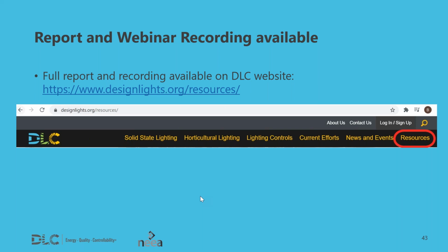Thank you. Yeah, I'm just going to add a little bit to that, in that one of the things that we see is that LEDs tend to be perceived as brighter, so when the new systems get put in, a lot of times they're lowering that trim down. It's not that it's a bad design, they put in the same lumens or whatever, but you do see that trim brought down because it feels too bright in there for the people. And I'd also say that there are a few manufacturers shipping products with trim already set at a certain level because of that.